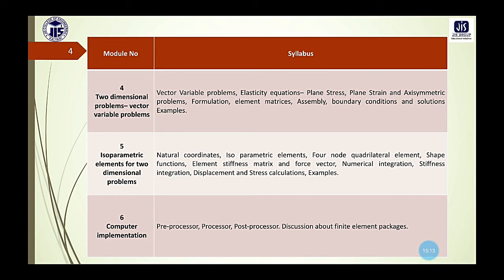In this pre-processing, a finite element mesh is developed to divide the given geometry into subdomains for mathematical analysis. The material properties and the boundary conditions are also applied there. So what is this mesh? What is the discretization? What are the different subdomains, elements, and nodes, and how do we put in the material property? What is the boundary condition, why will we use it, and where do we put it? All these things will be discussed in the pre-processing part.